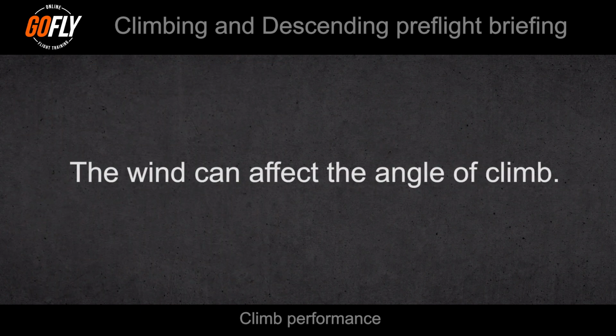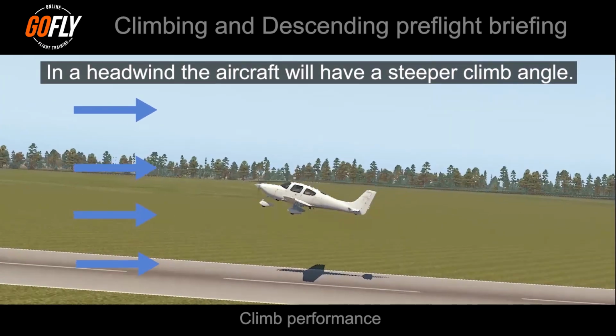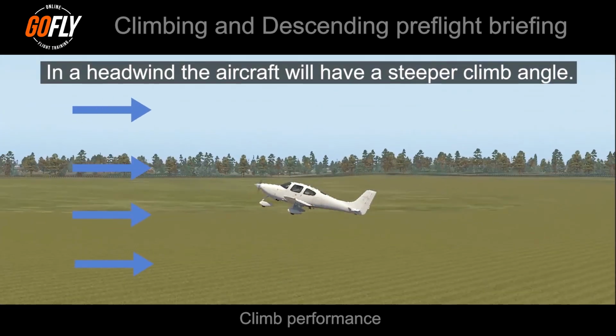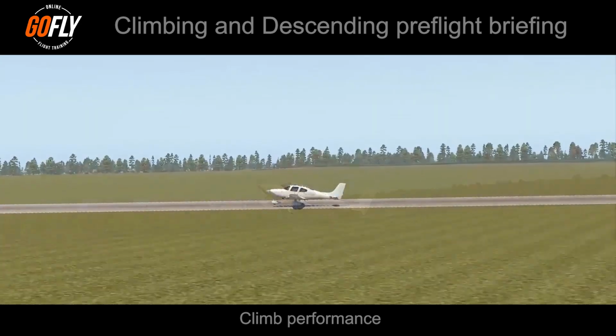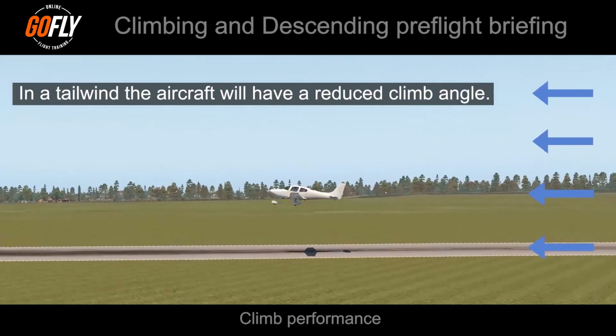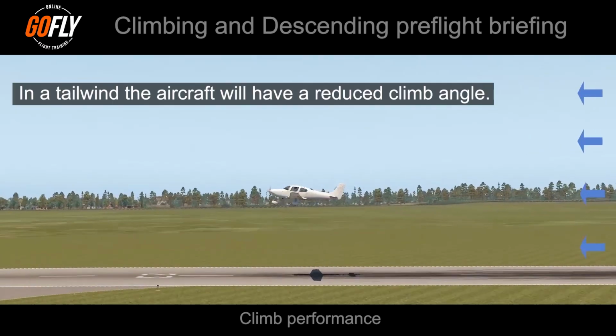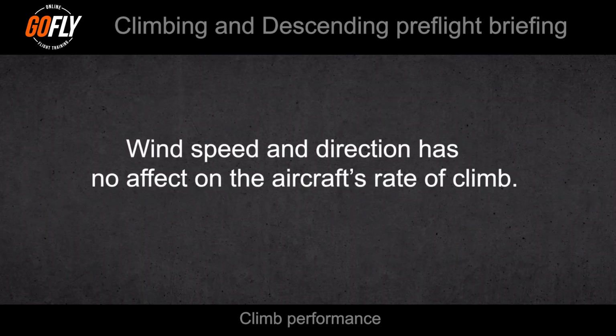The wind can also affect our climb. In particular, it will affect our best angle of climb. For instance, for the best angle climb in a headwind, the aircraft will achieve an increased angle of climb as the aircraft will be flying slower over the ground due to the headwind. If the aircraft encounters a tailwind, the best angle will be reduced as the aircraft will be travelling faster horizontally over the ground for the amount of height we gain. Wind speed and direction has no effect on the aircraft's rate of climb.